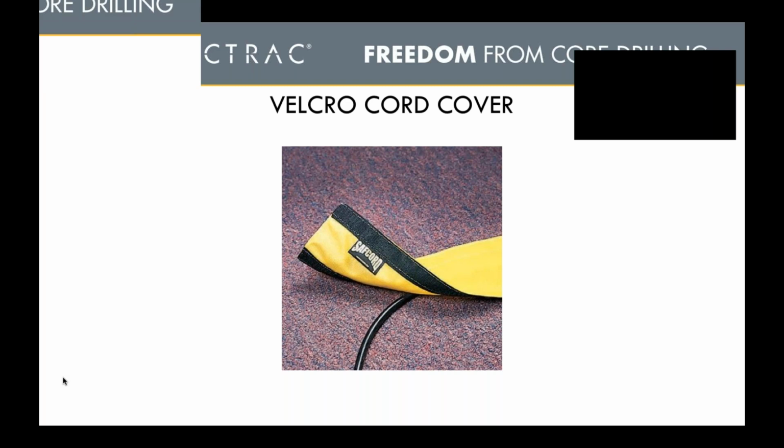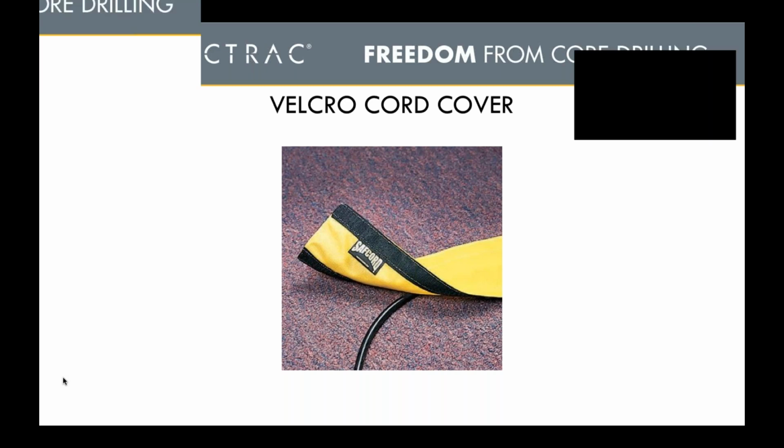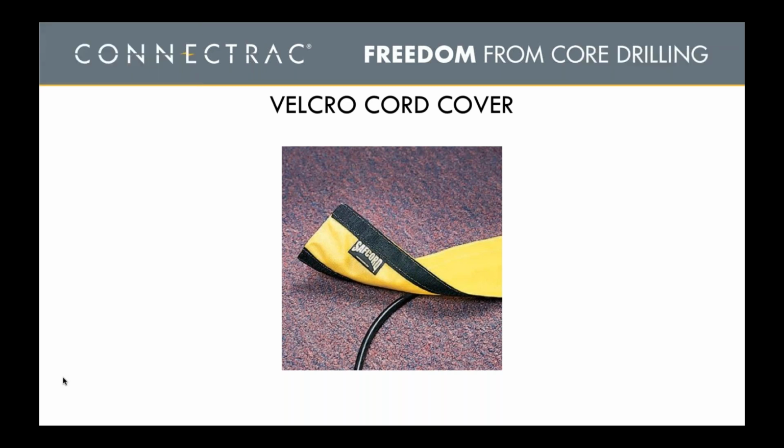Often we kind of cheat and we put these down because we are being asked to do something which is next to impossible, requiring that facility manager wizard. So this is why it happens. State Farm, which we all know, insurance agencies happen to have a lot of control, has an extension cord safety article. And in their article, they say two things that I want you to remember today. Never tape extension cords to the floor. And second thing, don't run cords under the rugs.